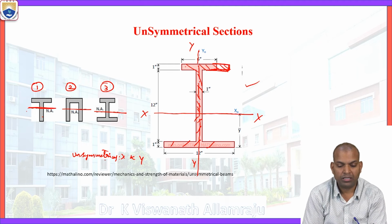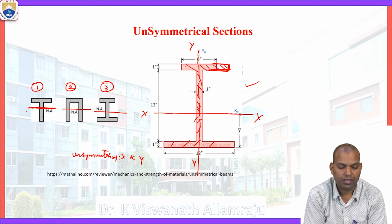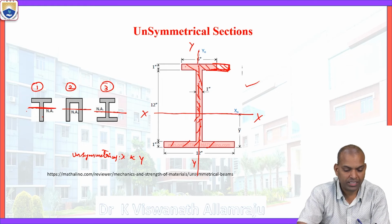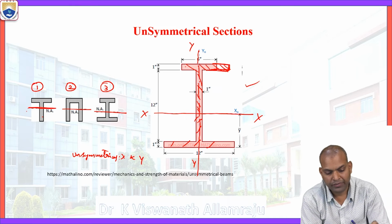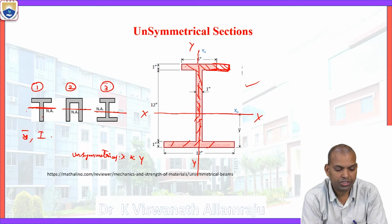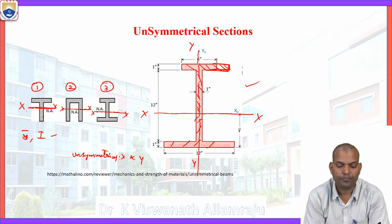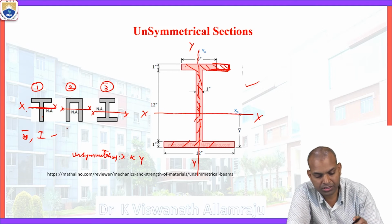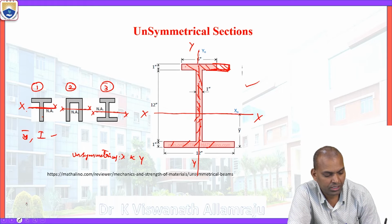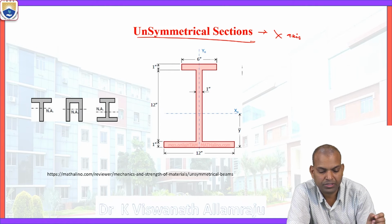So these are unsymmetrical sections about the x-axis. If we consider the y-axis, these are all symmetrical sections about the y-axis. Why do we consider unsymmetrical sections about the x-axis? Because in solving the bending stresses, we need y bar and moment of inertia I. These values we consider about the neutral axis parallel to axis x. That's why these are unsymmetrical sections about the x-axis. This is the concept here.